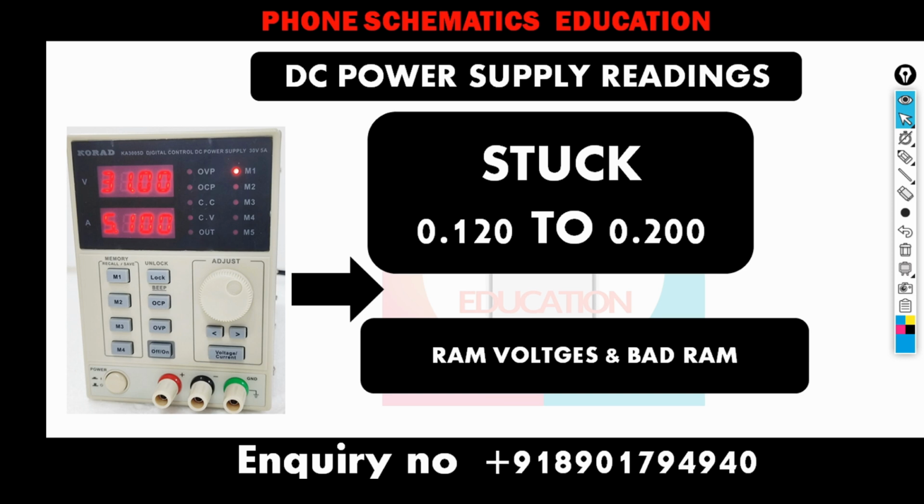Sometimes this problem goes to the CPU, because if the CPU does not respond to the RAM, a communication drop, same as with eMMC. Nowadays, the stuck problem is also caused by the CPU, because of communication loss between the CPU and the storage IC or RAM IC, then you will see these stuck problems.